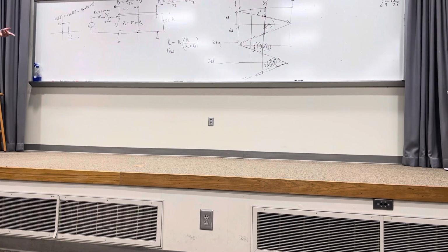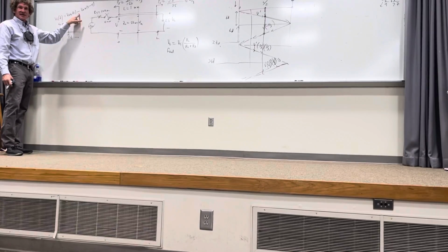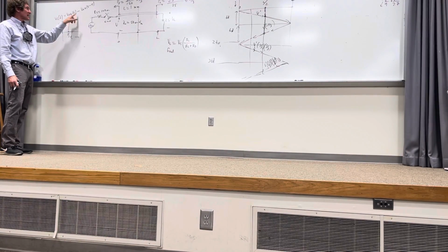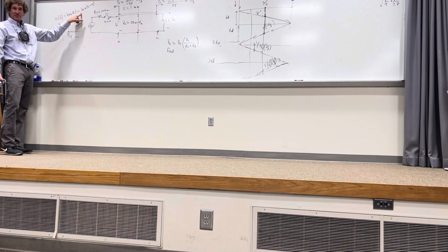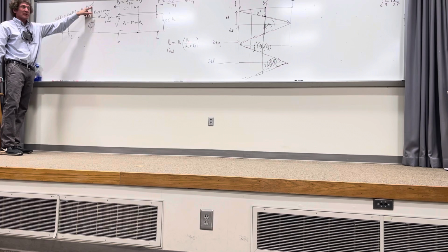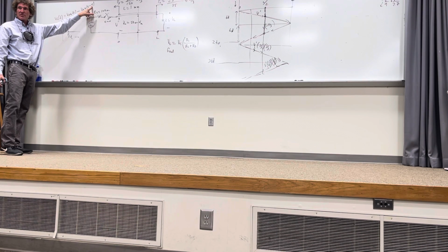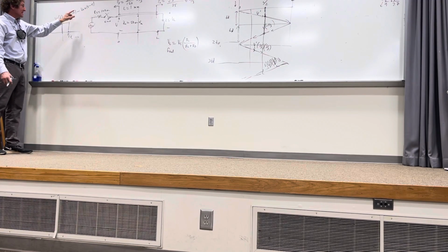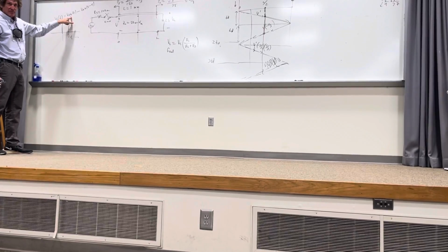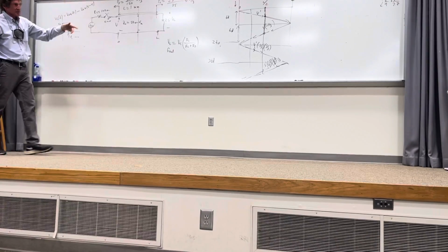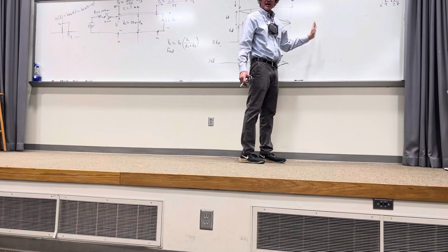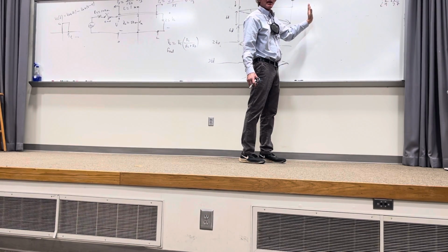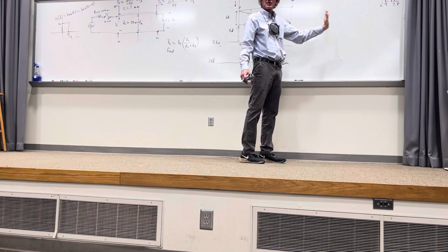So then the logical question is, well, what do you do with this? Guess what? You take the same exact waveform, or the bounce diagram for this, only now you put a negative sign in front of it, and then you time delay it by tau. Now if you want to, we can do that one, but it really isn't a stretch. It's just basically taking this waveform, and then you're going to get the bounce diagram, like the one we had up there, and you're going to subtract from it the bounce diagram, same exact bounce diagram, only now you just multiply it by a negative sign and shift it a little.